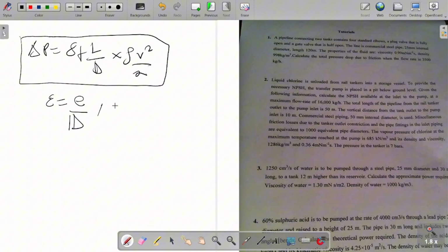But when we give you an outside diameter, if you want to get the internal diameter, we have to subtract two times the thickness of that pipe. So if you subtract two times the thickness of the pipe from the outside diameter, we get the internal diameter of the pipe. That's what we use to solve our questions, right? And over here too, since we are evaluating the pressure drop, we will also be evaluating power due to the pump or whether we are using a turbine, and we will also be evaluating NPSH for all these questions, right?